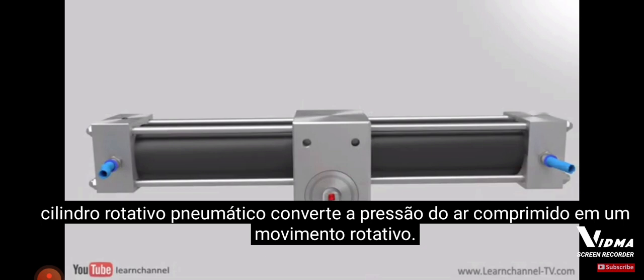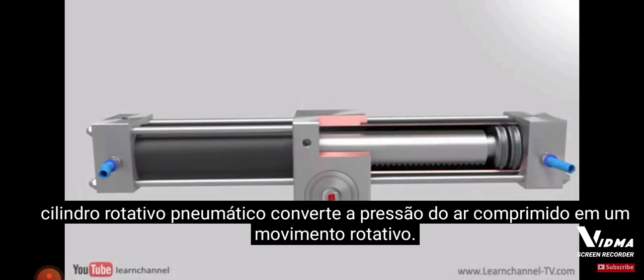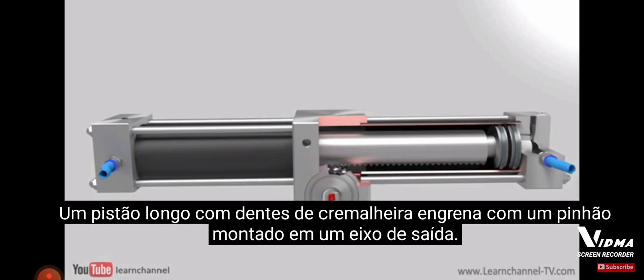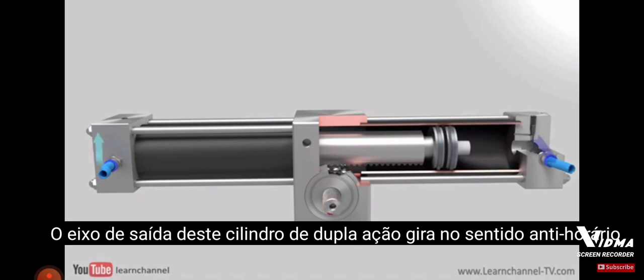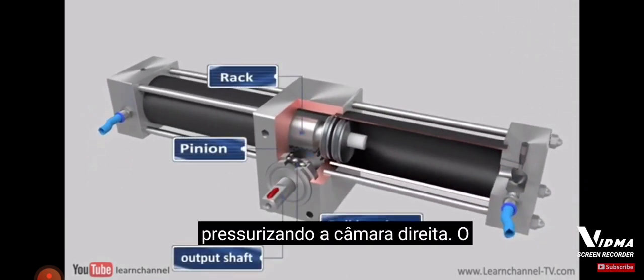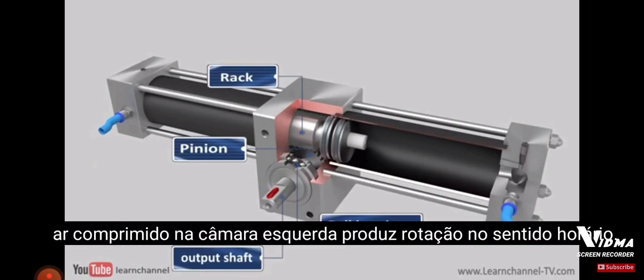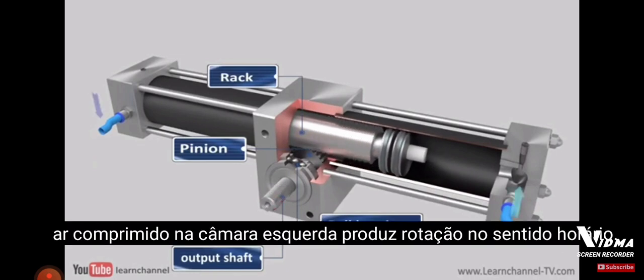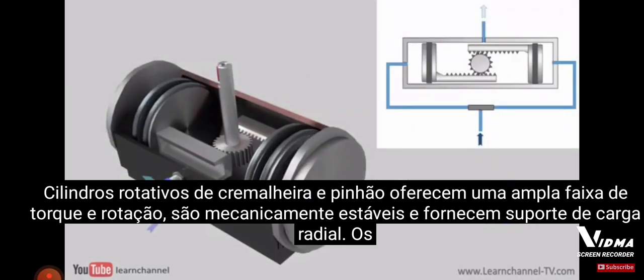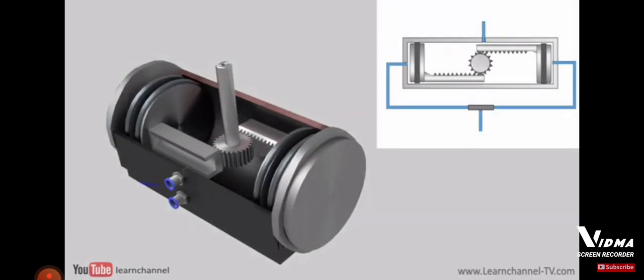A pneumatic rotary cylinder converts compressed air pressure into a rotary motion. One of the most widely used designs is the rack and pinion rotary actuator. A long piston with gear rack teeth meshes with a pinion mounted to an output shaft. The output shaft of this double-acting cylinder rotates counterclockwise by pressurizing the right-hand chamber. Compressed air on the left-hand chamber produces clockwise rotation. Rack and pinion rotary cylinders offer a wide range of torque and rotation. They are mechanically stable and provide radial load support.